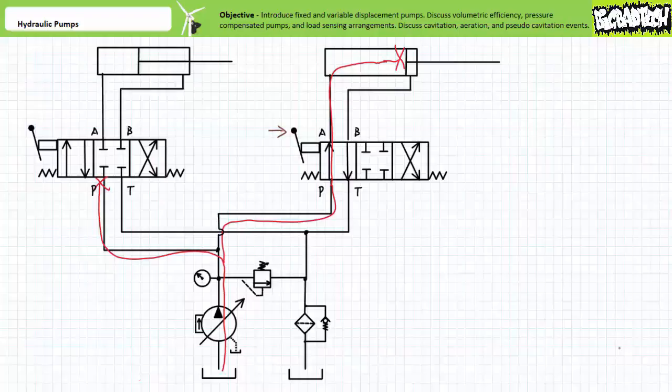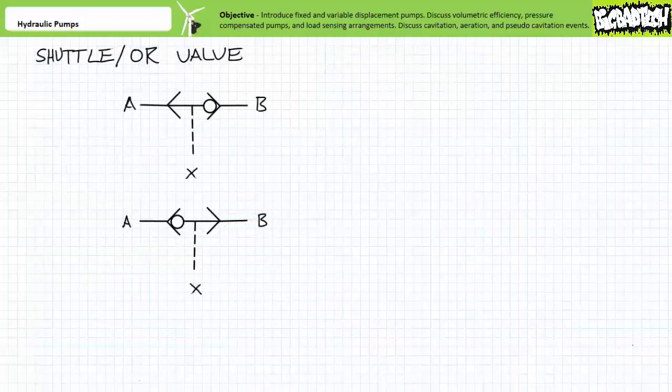Again, the advantage of this scenario provided by the pressure compensated variable displacement pump is that closed center valves can be used without the necessity of regularly actuating the main pressure relief valve, all the while allowing each actuator to operate independently of one another. Moving on, a closely related pumping scheme known as load sensing can be used to keep not only pressure but flow rate constant inside a given range.